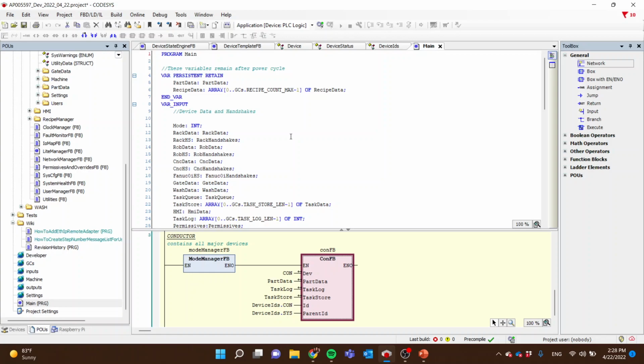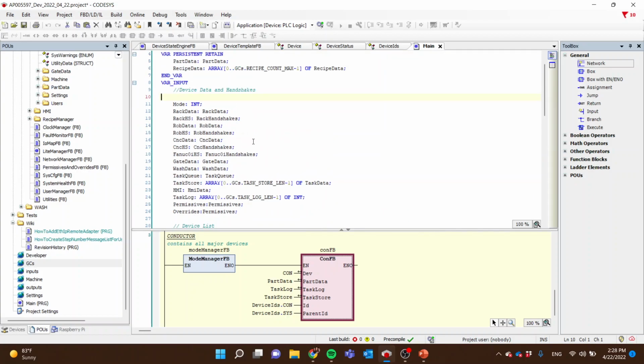In Allen Bradley, you have program-specific variables, and in our case, we have function block-specific variables. But the global variable, there's a couple ways to define them. You can actually create a global variable here, but more often than not, you're going to want to add it likely into main.